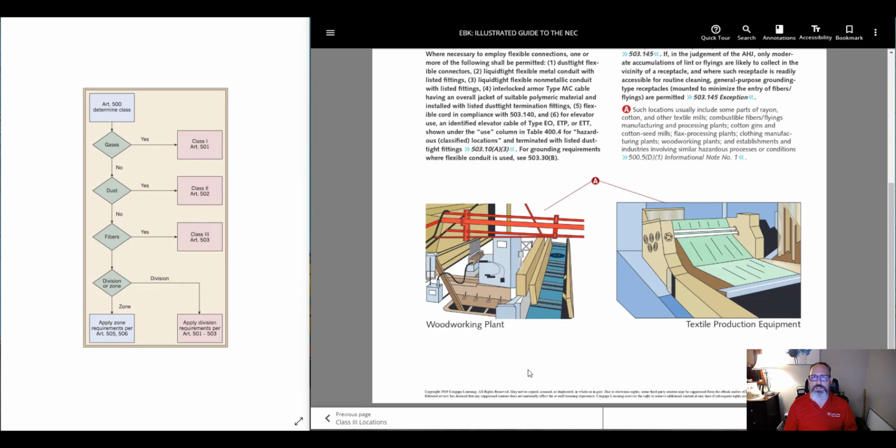And an inspection of the facility found that there was carbon fiber being produced, and everything close to the carbon fiber production area was what was failing. Carbon fiber is conductive. And so the dust goes in and settles inside of the equipment and the electrical drives and causes it to short circuit across the terminals inside. And there was dust in there. It wasn't just a theory.